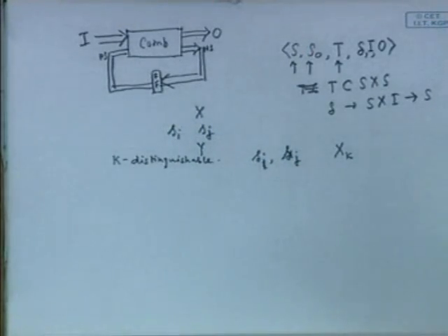If the input of length k determines that Si and Sj are not equivalent, that means they give you different output sequences, then you say that Si and Sj are k-distinguishable. And similarly k-equivalent, if an input sequence of length k gives you the same output sequence, then you say that Si and Sj are k-equivalent. Now using this k-distinguishable concept, we will do the state minimization.